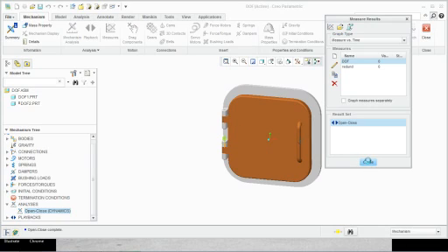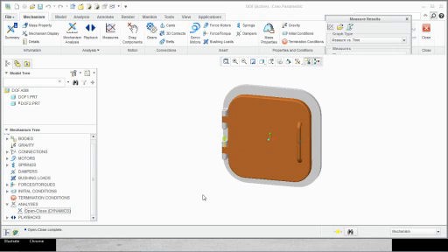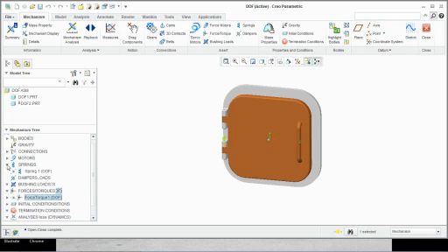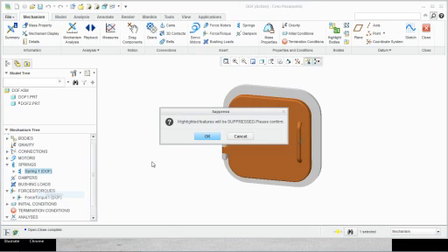Now what I do is I go here and I take out the force, say, or take out the spring. So let's suppress the spring. So there is no spring. And when I run the analysis, I also get rid of the force. So there's no force, nothing. So I run the analysis and then I look at the measure value.